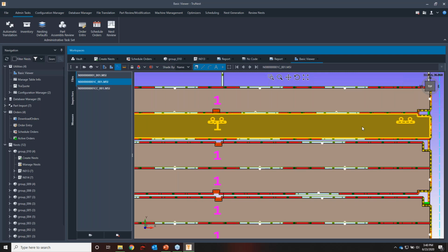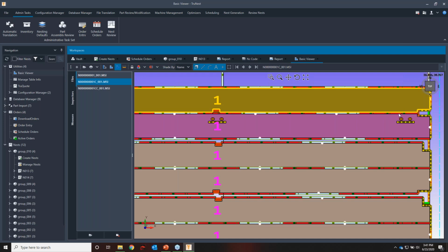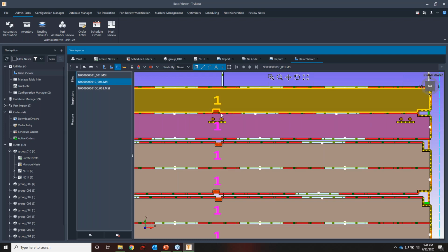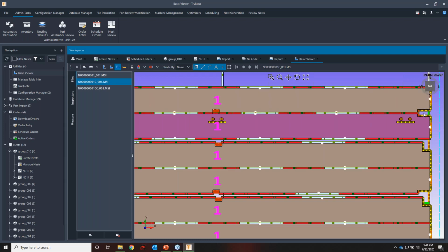Full common line solutions can be tricky depending on the part mix that you have. So if you have a lot of rectangular parts, full common line is actually very useful. But if you have a mix of parts that, some are more contoured or don't necessarily line up with some of the other parts, a limited common line solution will cherry pick the parts that it feels go well together and will start to leverage common line between those two parts. And what that does is it limits the amount of voids or areas between the parts where you have to destruct them. And it ultimately makes for a safer solution that doesn't necessarily need to be monitored as much as a full common line solution.